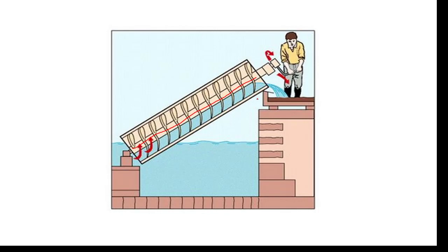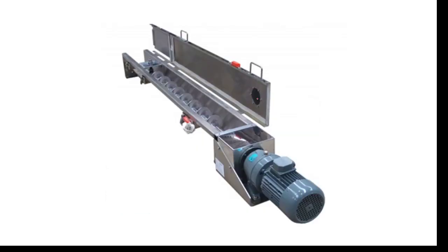Of course, today, not manually, but you can find in the market Archimedes pumps or conveyors or elevators. The rotor is driven by a motor. Here in this photograph, within this box, the cap has been opened. This is the main, valuable part. It's an Archimedes screw. And here, this is the driver, an electrical motor. It rotates the Archimedes screw. So at this end, the particles are taken away and then move in the direction.